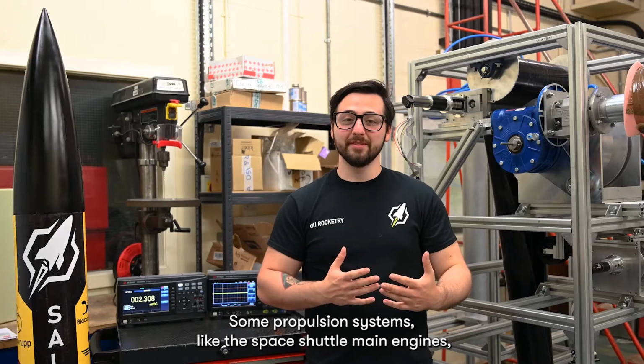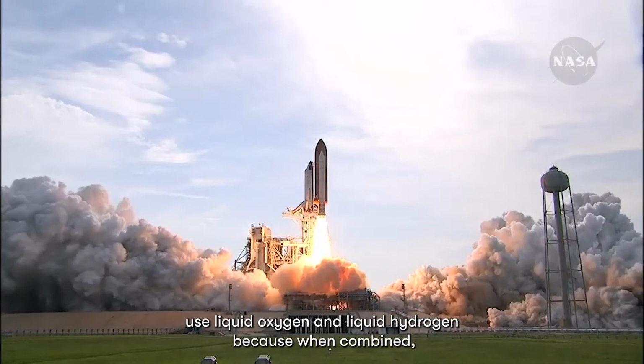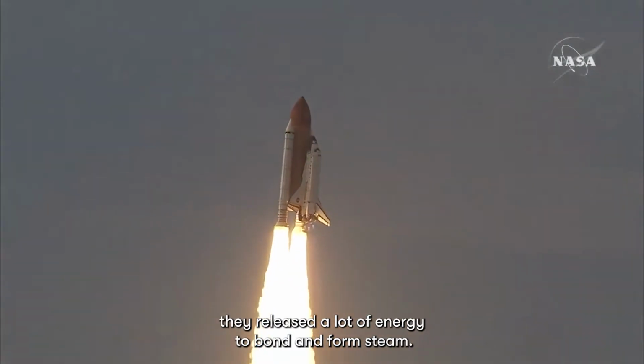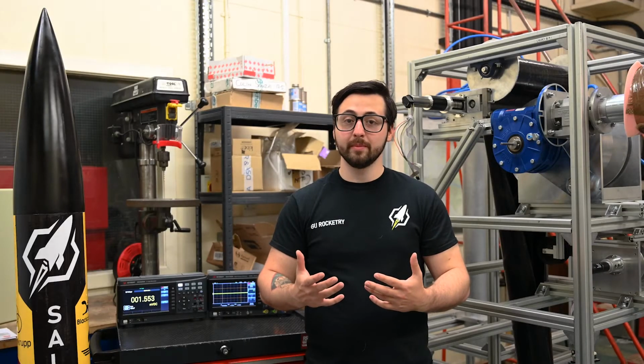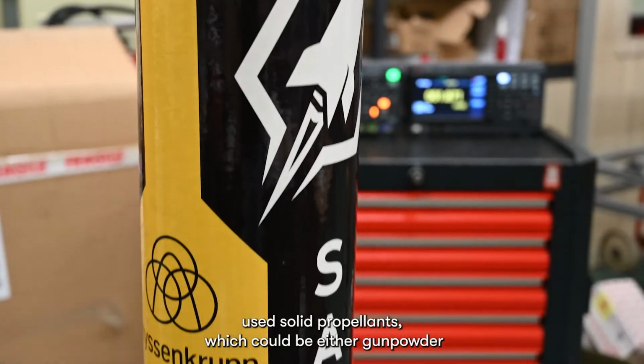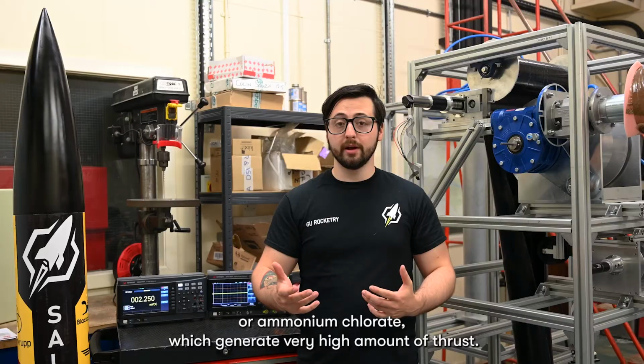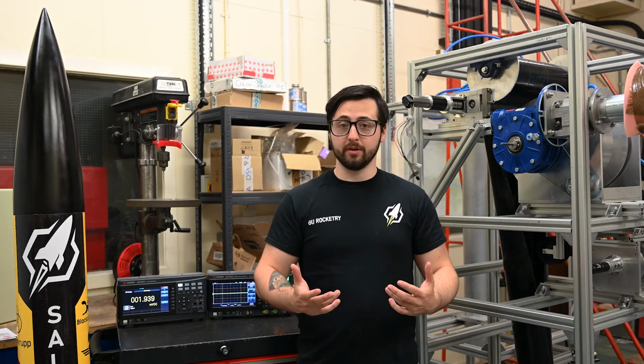Some propulsion systems, like the space shuttle main engines, use liquid oxygen and liquid hydrogen, because when combined, they release a lot of energy to bond and form steam. Other systems, like our Saltire 1 rocket here, use solid propellants, which could be either gunpowder or ammonium perchlorate, which generate very high amounts of thrust.